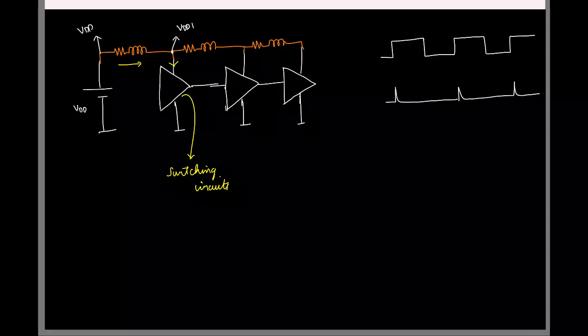Because of the presence of this inductor here, the supply voltage will see huge jumps. It could easily happen that these jumps are so high that the transistor connected to these points can go out of saturation. So this is a serious problem. So what do you think we can do to reduce its effect to some extent?